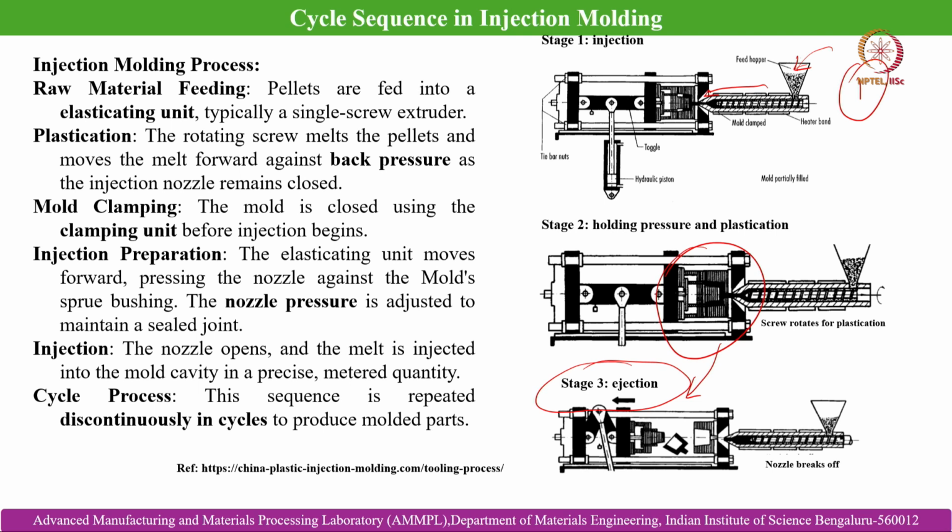In the case of polymer, this is the final part that we get from this stage, and in the case of metal or ceramic injection molding, this is only the green compact, which then needs to be further processed via debinding and sintering to achieve the fully dense part for in-service applicability. So, this is how we implement the injection molding process.